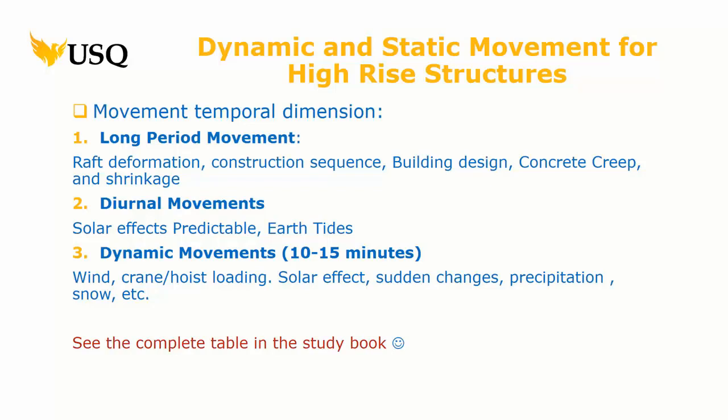Precipitation, that's a big word for rain, right? Which we have a lot of. Snow we don't have a lot of, but that's why you see chalets with steep roofs, right? Because they cause deformation if you've got a flat roof. In Australia, for example, because we look at cyclones, we tend to have gone to strengthening the building. In the past, it was to let air through, to change the pressure. Whichever way the wind was blowing, you would open the windows on the opposite side to remove the pressure from inside the house, because that's what used to blow the roof off. Now we tend to actually just tie the roof down a bit better.